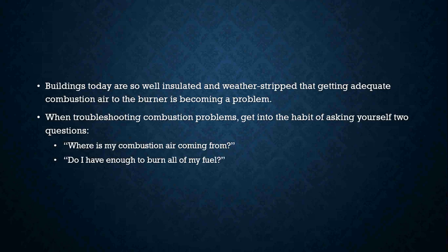When troubleshooting your combustion problems, you have to ask yourself those two questions that you see here. Where is my combustion air coming from? Is it coming from my surrounding area? Is it in the room? Or do I have enough to burn all of my fuel? You've got to get thinking that way when you're looking at a burner or a boiler or whatever it is that you're looking at, because air is a big part of it. Do I have enough air?